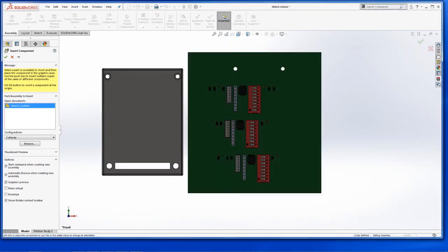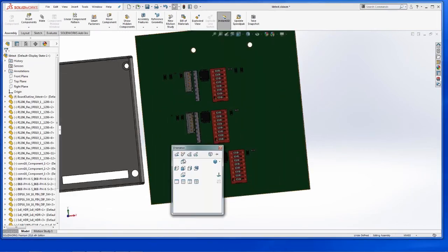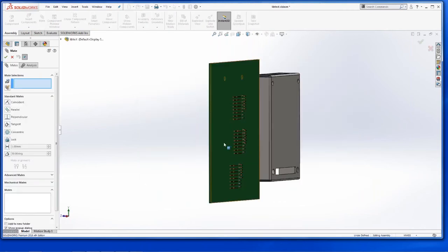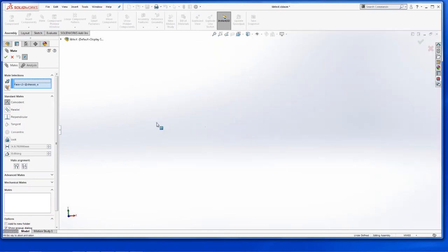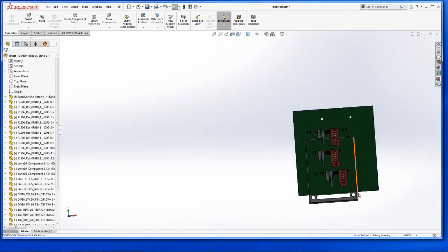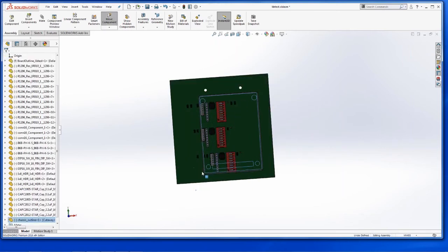Okay, and again, you can see that they're not referenced. Definitely the board part is not the right size. So I would use SOLIDWORKS to make these modifications. Reference the two items together and position the components and the mounting holes onto the standoffs. Again, that's done simply by just creating a simple mate. So we take the back of the board and we can put that right on that surface. Okay. So now I've got my chassis in my assembly, and it's now referenced correctly.